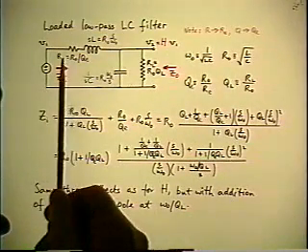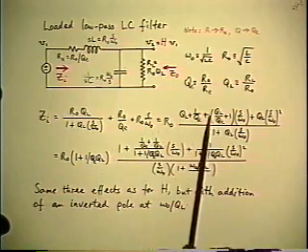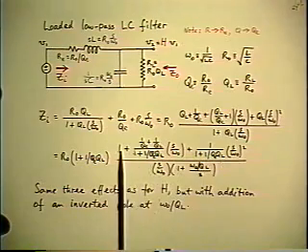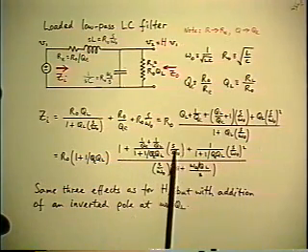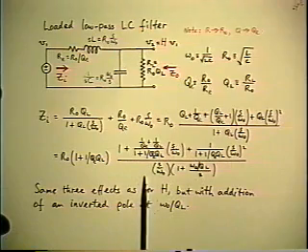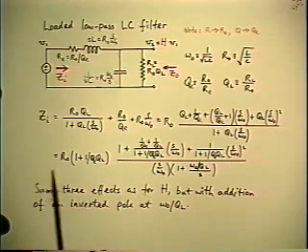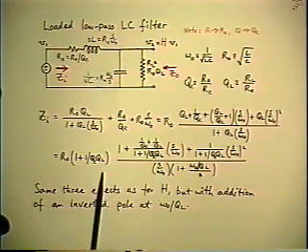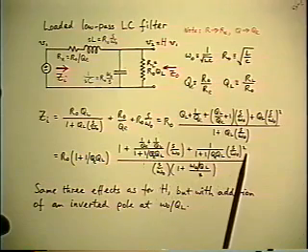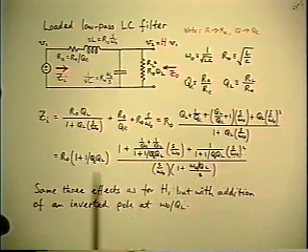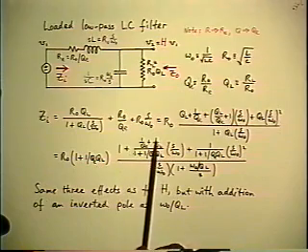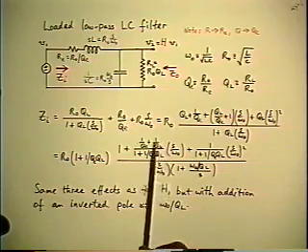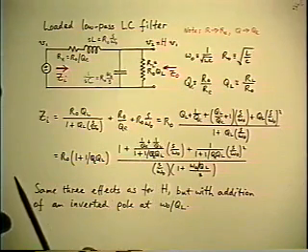Input impedance is the sum of the various elements, and again, in 3 lines, you get the full result, in which you have the full quadratic, which is moved again to the numerator from the denominator. So you get the same 3 effects that we had before, 2 of which are second order, which means you can simplify the quadratic to the same earlier version. You make the leading coefficient unity, and the only first order effect in the quadratic is the total Q factor comes out again as the parallel combination of the 2 contributions.